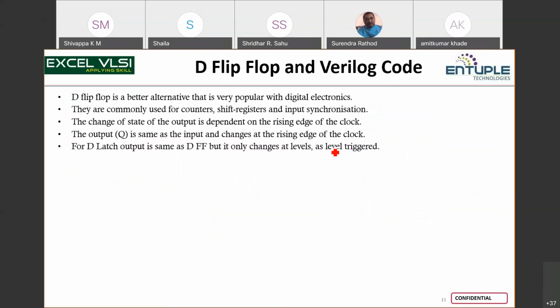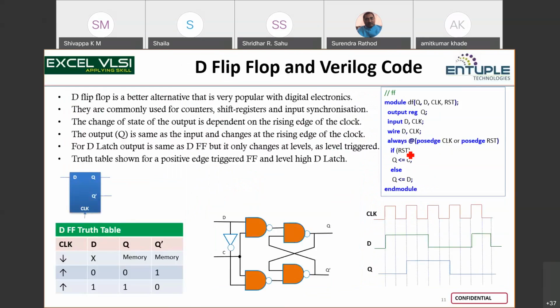So the flip flops I have modeled here. Okay, so D flip flop Verilog code, right? And how the output follows the input in the D flip flop. For example, now in this clock, D is 0. I come to the timing here, setup time, it has missed this one, okay, which will be captured in this cycle, and then D is 1 in this, right, like this.